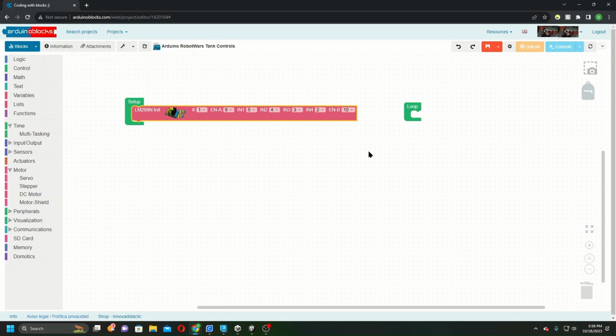And then pins 9 and 10, the reason that's skipped there is because you'll notice on this pull down, there's only certain pins available. These pins are the ones that will allow you to communicate with the motor controller in the way we need. The reason these pins are the only ones available is because on the Arduino, if you look on the sides of the pins, you'll notice that some of them have a tilde or a dash next to the number. That means that particular pin is capable of pulse width modulation.